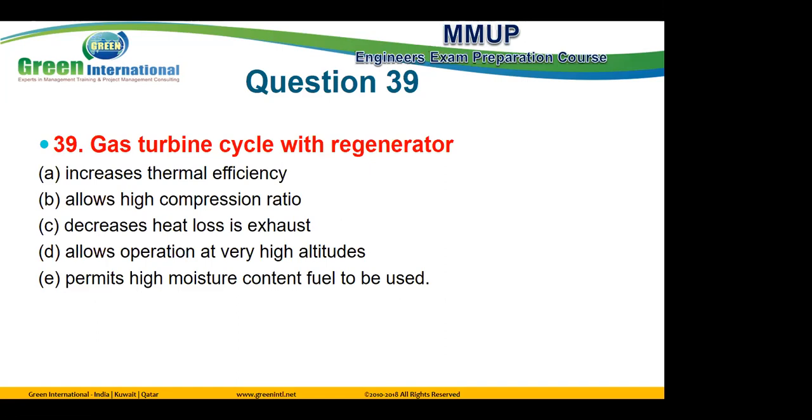The output of the compressor is air, still at low temperature, going to the combustion chamber to mix with fuel, burn and obtain energy. So before the air goes to the combustion chamber, I heat exchange this air line with the exhaust of the turbine before I lose this exhaust.